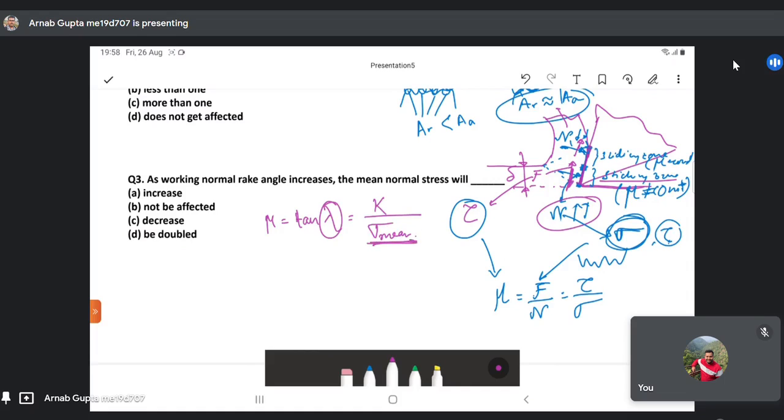This is the mean stress, mean normal stress, or the compressive stress, which is acting on the rake surface, and K is a constant which includes the shear component of the stress, and some other information like the length of contact. So all those can be fairly assumed as constant over a larger range of unlubricated conditions. So using lubrication you can reduce that. So that's why I'm saying it's unlubricated condition, and it has been seen it is constant for a given material over a large range of cutting parameters. So this is constant.